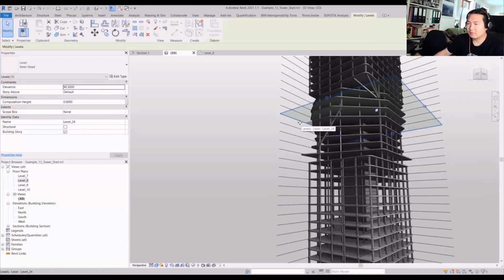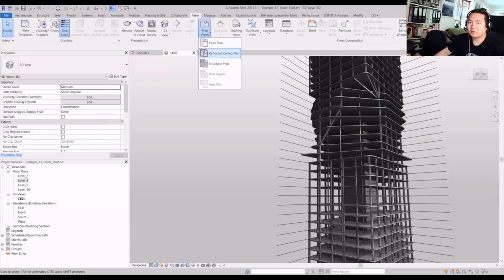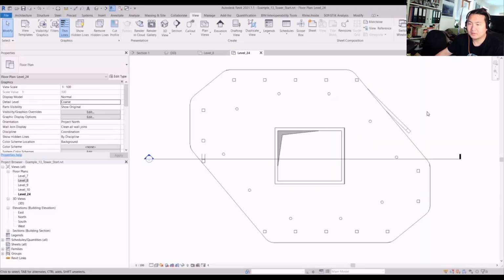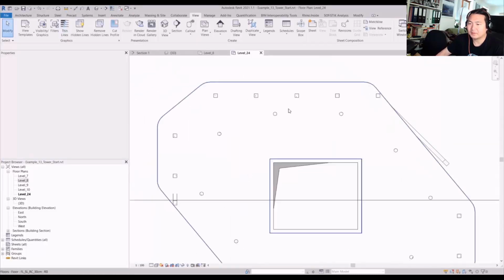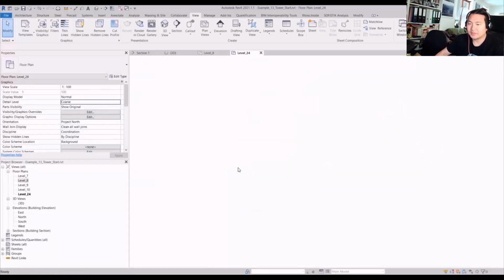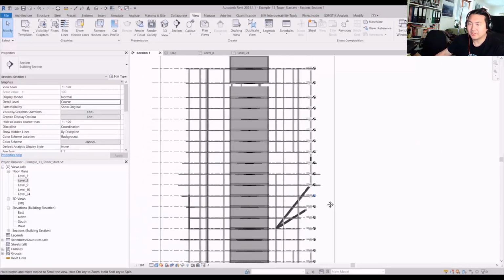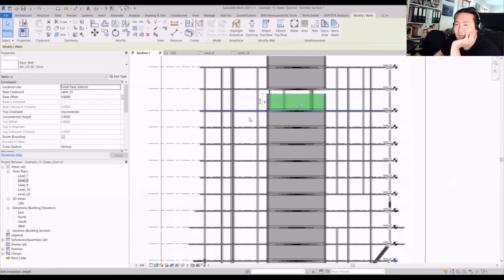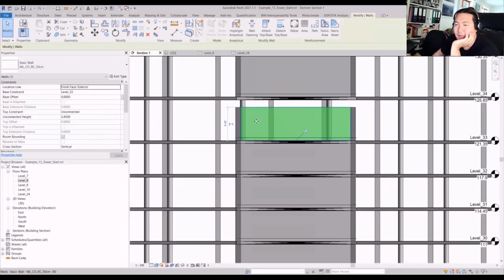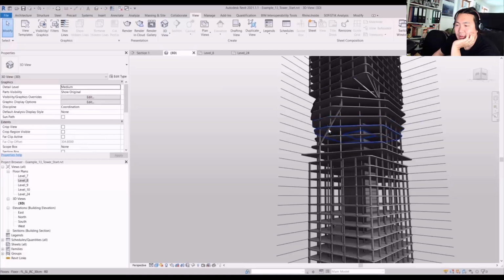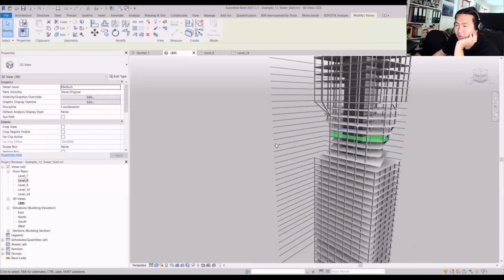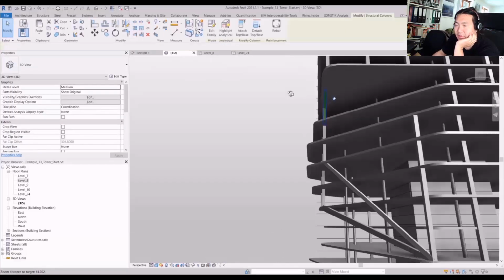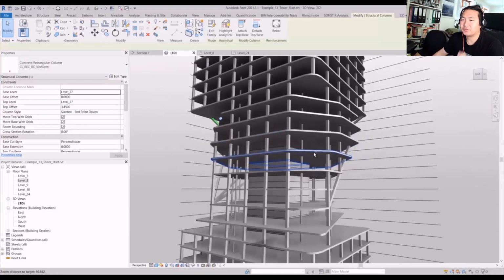And according to the BIM model, your data attributes are updated. If I generate some new floor plans, as you can see, the floor plan is also automatically updated. And when I go to the section view, you have completely new section geometry generated. There is a small mistake in the data structure to offset one of the floors, and you can just work on a short Grasshopper definition to fix that error. And apart from that, the model looks really great.